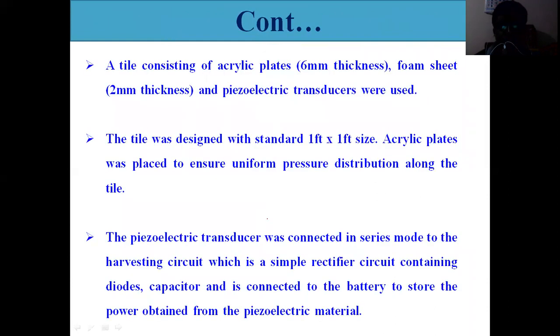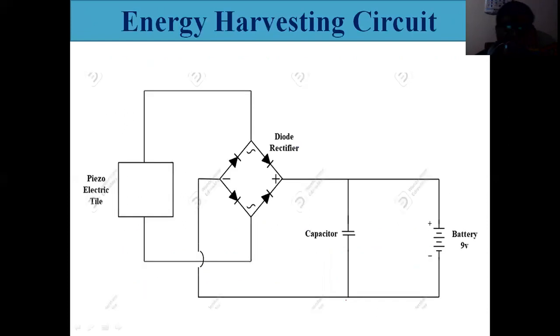Configurations: the piezoelectric tiles were connected in series or parallel mode to the conversion circuit, which is a simple rectifier circuit containing a diode and capacitor, connected to the battery to store the power obtained from the piezoelectric material. Finally, we can use it anywhere.